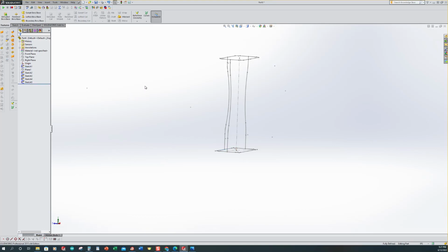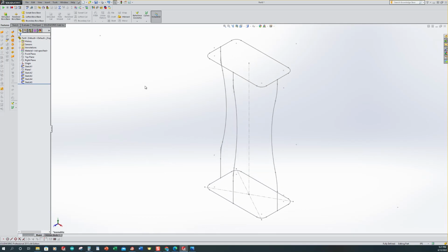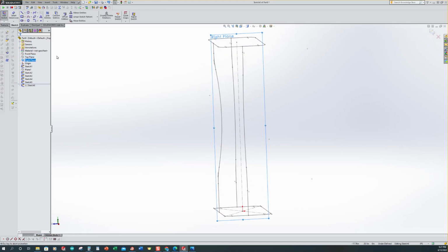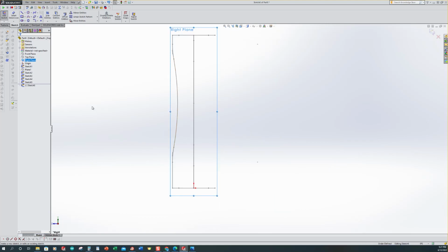Click out in the modeling space, Control 7. So we now have 5 sketches. You can hover over them and they'll turn orange, kind of show you what's going on. So we want to do the same thing as we did here. We had to mirror it across, okay? So we want to come to the right plane, click on the icon, flyout pops up, select sketch command. We want to use a Control 8 to normal to us.